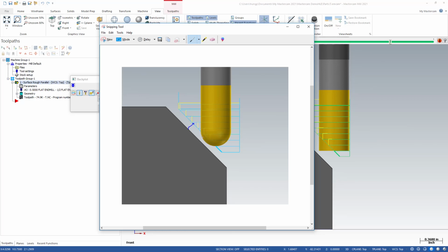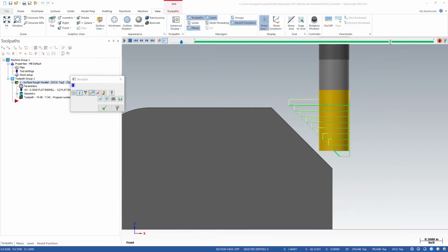Ball anvil, this area is not very strong. It's not meant for heavy cutting. So you will put too much load if you do that on the ball anvil. It's easier to do it on the flat anvil because flat anvil can take a lot more load. In addition, you can see this ram. The flat anvil travel this direction, so it will clean up the steps for you.